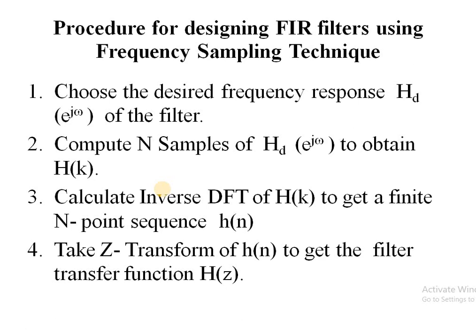Before directly starting with the procedure, I would like to add some points on where the idea of designing FIR filters by the frequency sampling technique comes from. In this method, the ideal frequency response, that is, the desired frequency response, is generally sampled at a sufficient number of points, that is, N points. And these samples are the DFT coefficients of the impulse response of the filter. Hence, the impulse response of the filter is determined by taking the inverse DFT in this case.